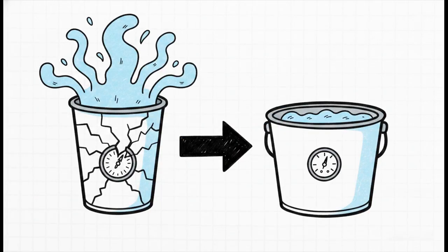Which brings us right back to our mystery with Arjun. Why did his lead tell him to change that specific line to Schedule 80? Well, instead of just guessing, Arjun actually goes back to the process data sheets. And what does he find? He discovers that a quiet process revision had bumped up the line's operating temperature and pressure. When he recalculates everything, his new required thickness, plus his corrosion allowance, suddenly exceeds the physical thickness that Schedule 40 could provide. Schedule 80 was simply the next standard bucket available that safely covered that new mathematical reality.